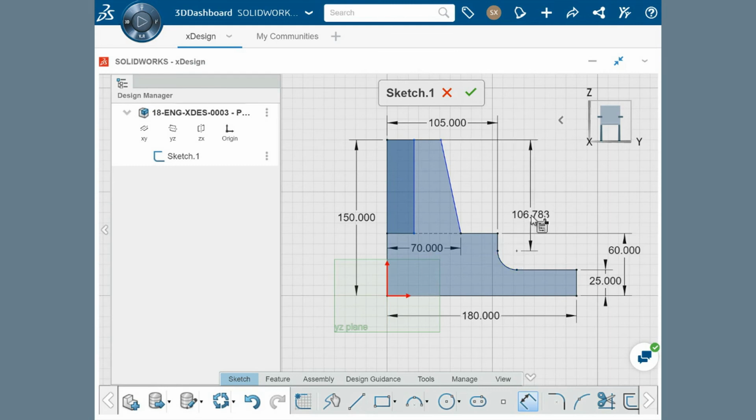few different ways. I can set the horizontal distance between them, the vertical distance, or the direct distance between the 2 points. I'll set the direct distance in this case. This distance, however, was just to show you the options when dimensioning between 2 points, so I'll click Undo to